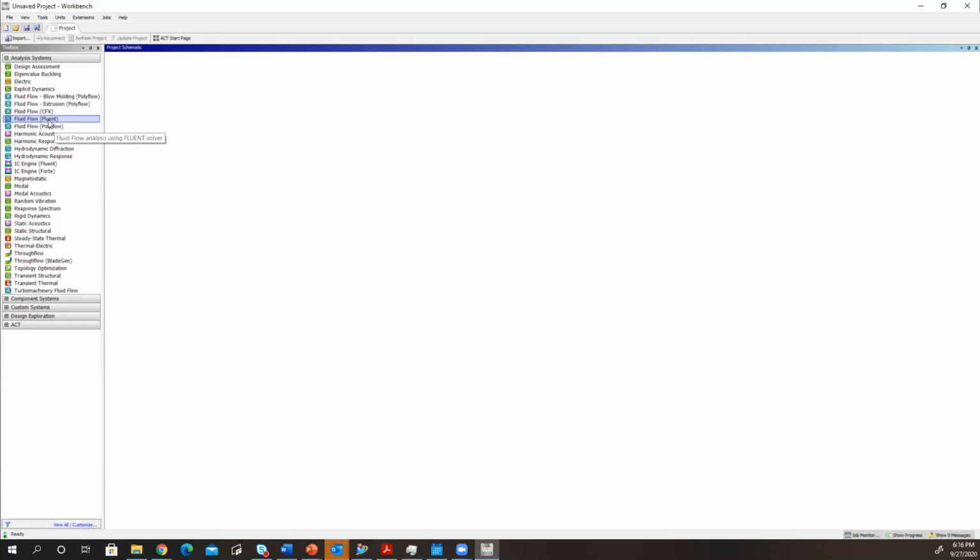But anything dealing with statics and mechanical solid stuff, you use ANSYS Workbench, right? The module that we're going to use is called Static Structural. So you just click and hold, drag it, and let go. Then this little step process is going to show up.